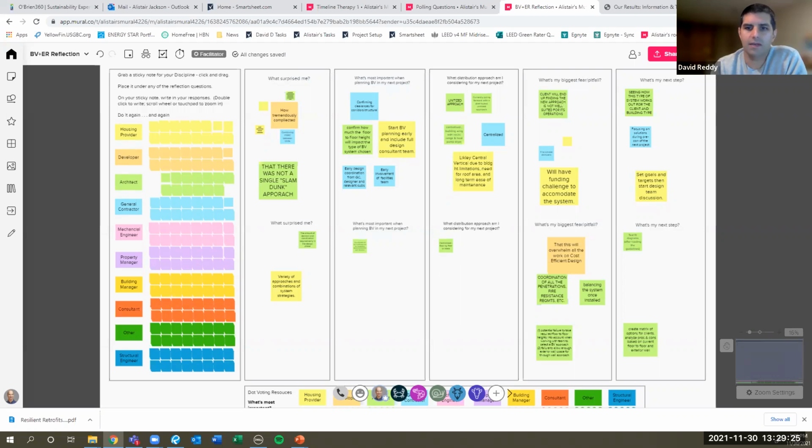So yeah, it's recognized, and also the exemplary building demonstration projects included energy studies, and balanced ventilation with heat recovery is the second highest impact measure to implement in terms of energy savings and carbon footprint, after heat pump water heating. I've certainly been pretty surprised with the impact that we've seen in the modeling of balanced ventilation with energy recovery, because I hadn't necessarily anticipated that in the old days.